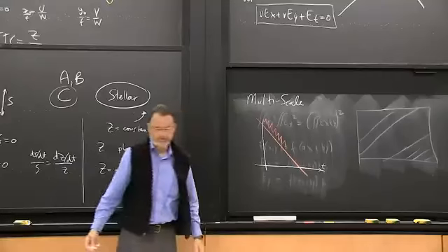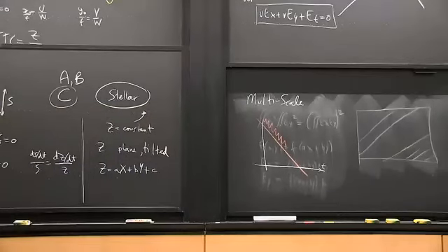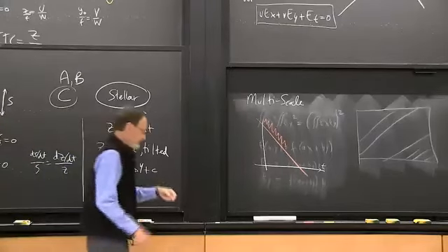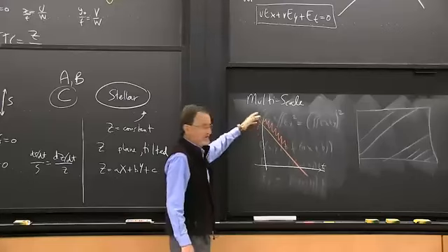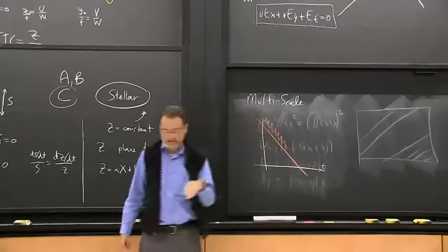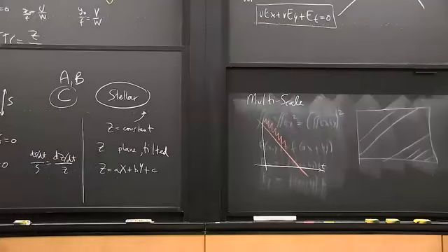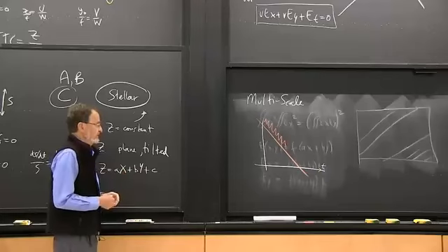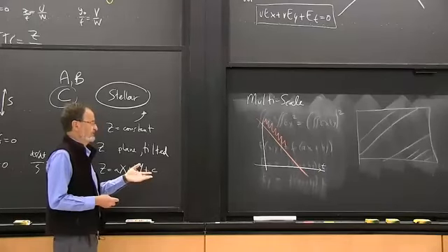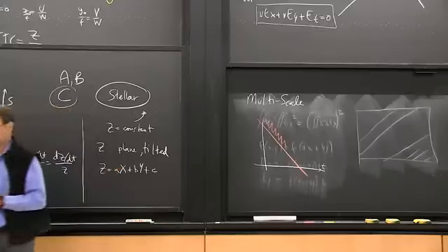Noisy. That's partly because the measurement of the position was not very accurate. It was eyeballing down on a measuring tape. There was an interesting offset vertically, so there's a bias. So it's not just noise. Actually, the estimated time to contact was overestimated, which in itself isn't good because you're about to crash into something. You don't want to be told that actually it'll take longer than the true time. On the other hand, since it's a systematic fixed bias, you can compensate for it.